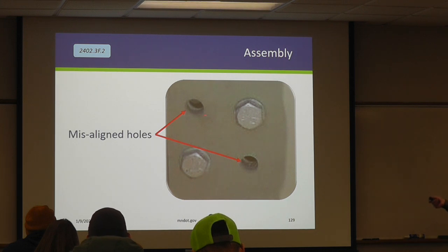Here's those misaligned holes, kind of a blurry picture. So this is after, I think about 40% of the bolts were put in. So you would think this should just be a 1/16 of an inch slot, right? There's that much flexibility in this place that we got that far off. So they had to take all the bolts off. That's extra work, extra time, right?